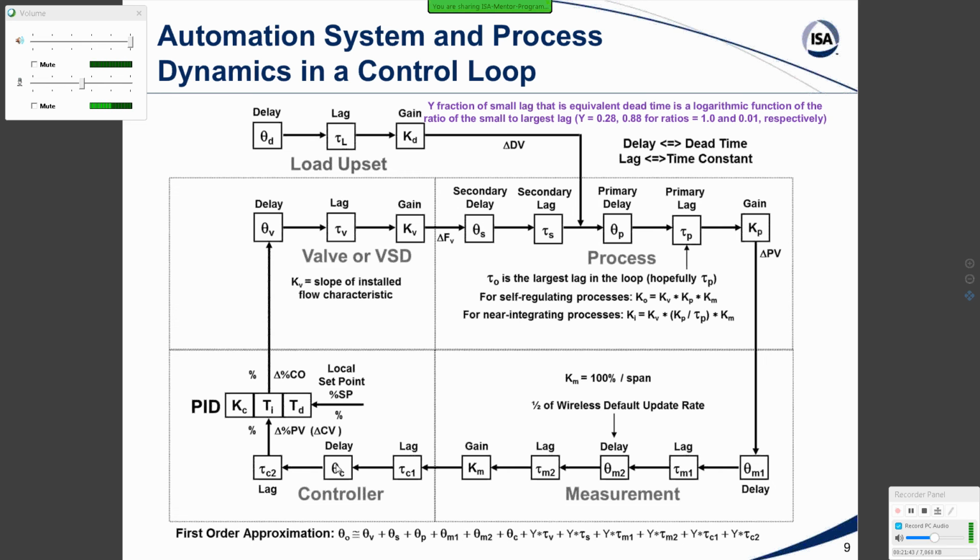It could be the delay associated with the execution of the controller, or the delay associated with the response of the control valve, which we've seen can happen for particularly poor positioner designs or for valves with a lot of stiction or backlash. Anyway, it really is useful to understand where the dead times come in. You want to find the biggest source of dead time and reduce that.